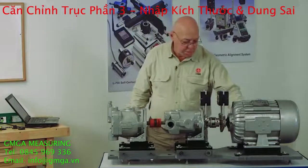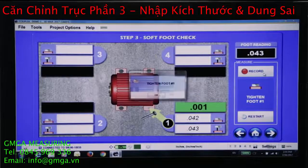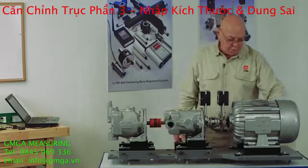So I'm going to loosen that bolt, and I'm going to record that. And then it says, okay, tighten that back up. So I did. And now it wants me to take a reading again with all the feet tight. I record that. And now loosen this bolt.